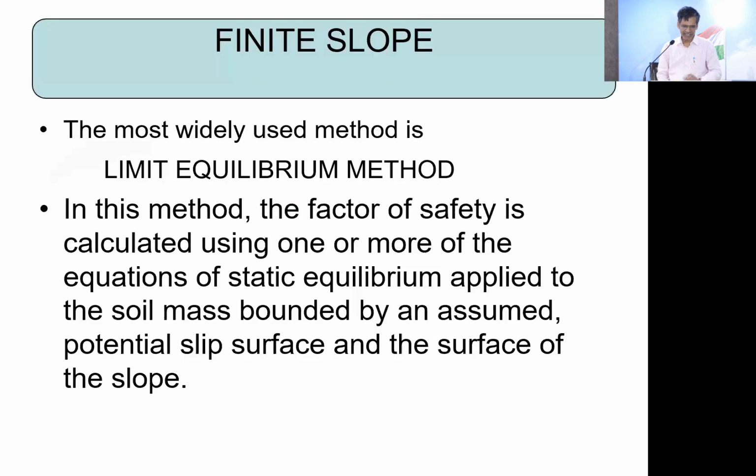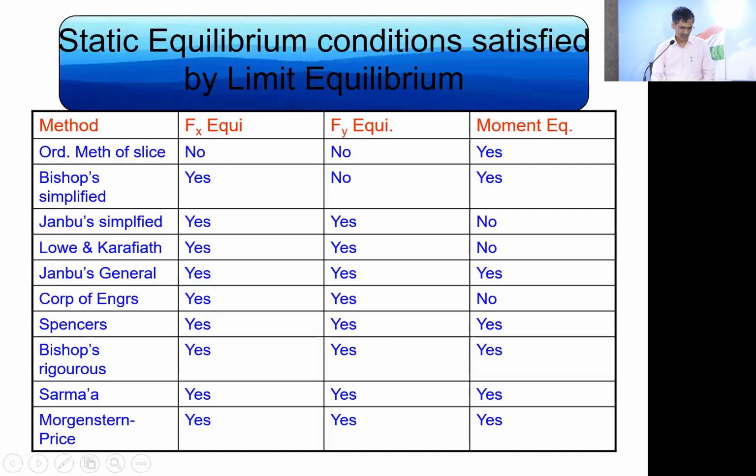Okay. So this is the limit equilibrium method, I say Fellenius method. There are so many methods. If you go to software, there are so many methods, and GeoSlope, Corps of Engineers, all of them are there. So which method will you go for? For me, mostly it is Bishop's simplified method. Somewhere we get confidence with Bishop's simplified method. But all these methods are there, and they may give a different value.